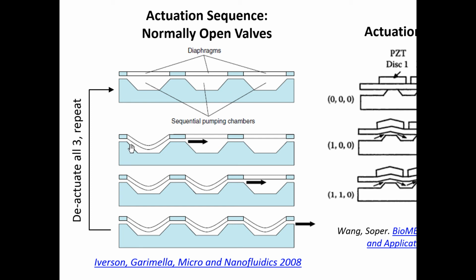Okay, this diaphragm gets pushed down, and as it does, it pushes fluid this way. Now keep in mind, this is also going to push a little bit of fluid backwards. Because if you displace the diaphragm, you're going to get flow this way, and you're also going to get flow the other way. Okay, so a single diaphragm just going back and forth is not going to be able to generate unidirectional flow, like we talked about earlier.